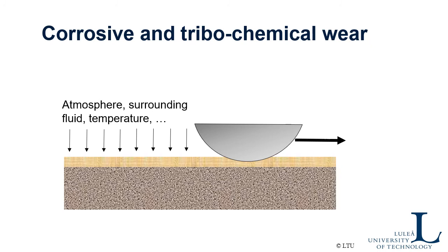And during the oxidation, you do of course consume the base material down here, so it's a wear process itself. If you wear off the formed oxide layer very rapidly, you wear the surface very fast. So you can have a very fast wear process due to corrosion.